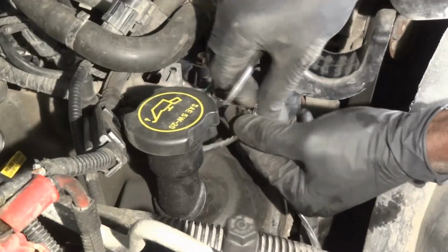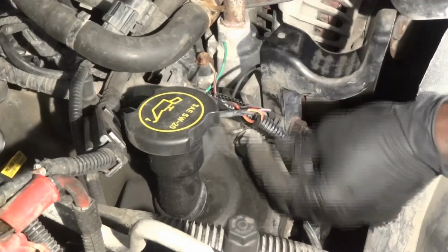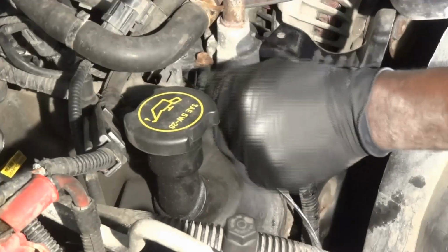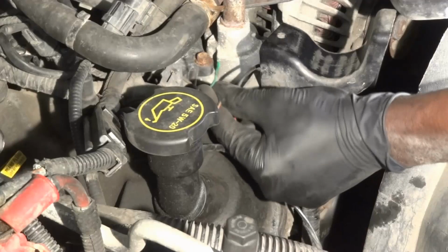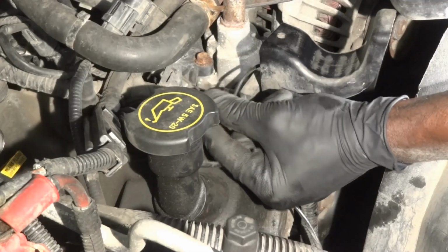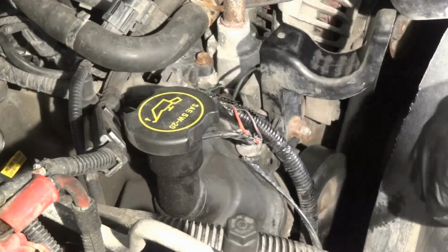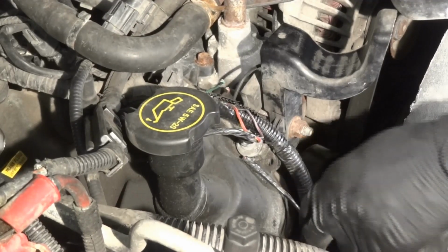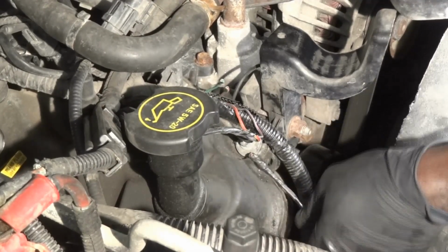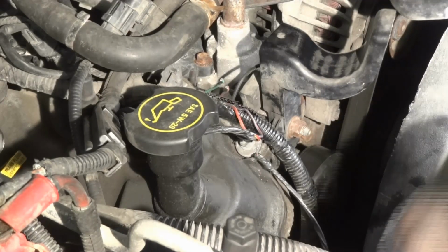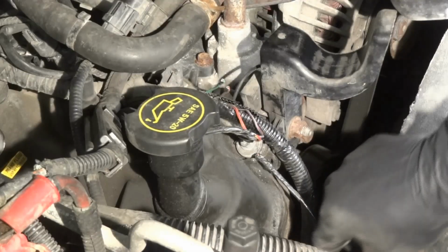So we got both of our cam sensor wires up here. So that's good. That's long enough. Okay, these wires are long enough. This will allow us to fix these two wires. So now we're gonna remove the tape on the sensor side. Actually, I can just disconnect the sensor down here and remove this connector.